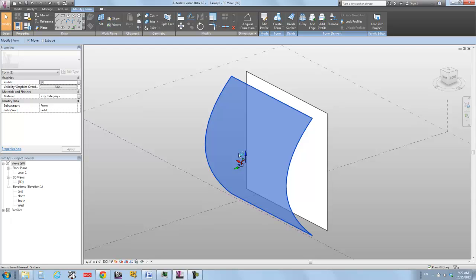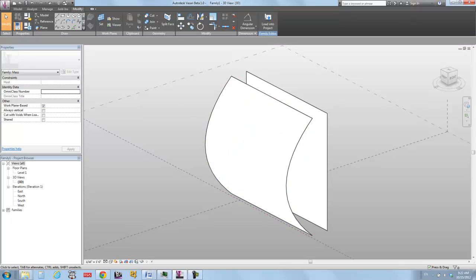When you select the element, you can do things like copy and drag. But when you just select the face, no such luck. So I'm glad that you brought that up, because you can deal with that by looking down here in the lower left, the status bar. You can see that right now I'd just be selecting the surface, which would not allow me to copy. If I tab, I can get the element, or if I box select, I'll get the whole element.